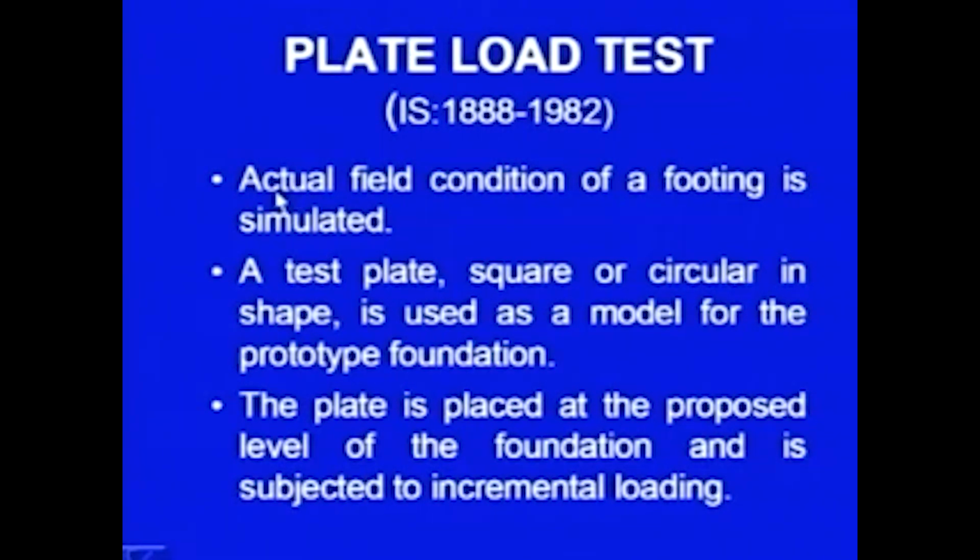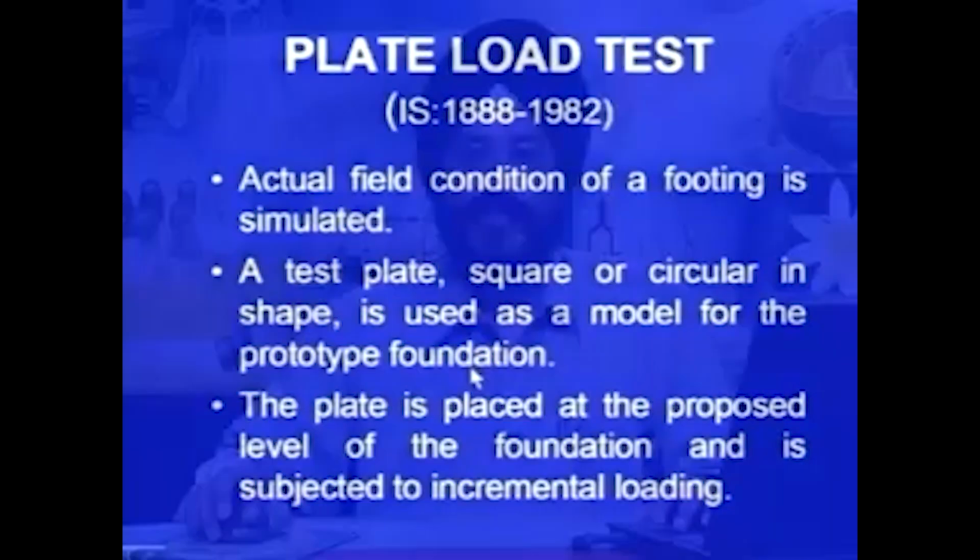And in this test, the actual field condition of a footing is simulated. We try to do the same thing as an actual footing does in the field. What it does is that it applies a load on the foundation, there are settlements. So, we try to simulate those conditions. So, here a test plate which is square or circular in shape is used as a model for the prototype foundation. The foundations may be rectangular, foundations may be square.